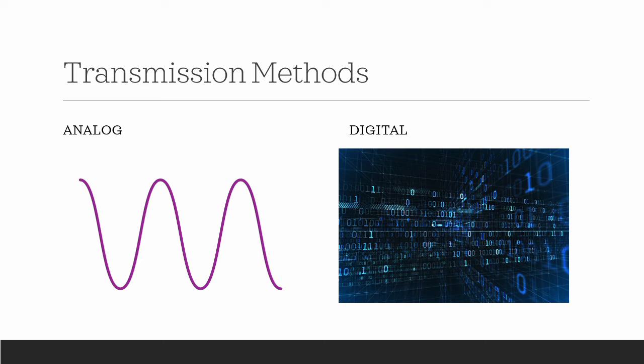The other thing I want to point out with our digital systems, as we get off that tangent, is that digital systems are less susceptible to RF noise, and less susceptible to high frequency losses. The other feature that digital systems offer, which is really nice, is encryption. If you're in a situation where sensitive topics are being discussed during your presentations, we don't want anyone outside of your event space hearing that information, so we're able to encrypt the broadcast signal.